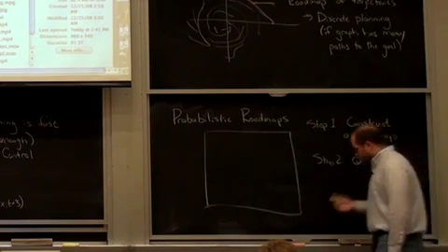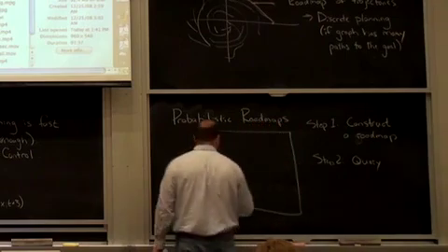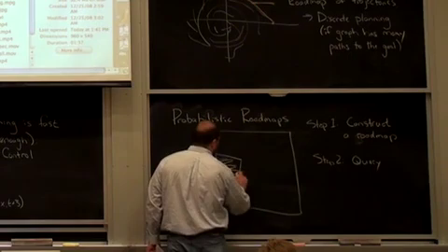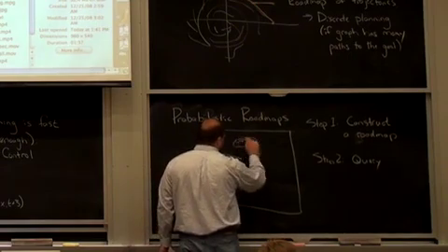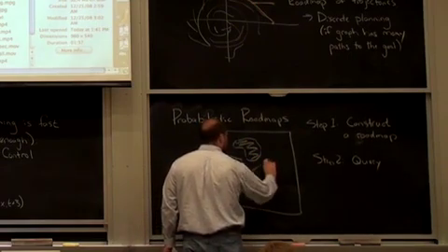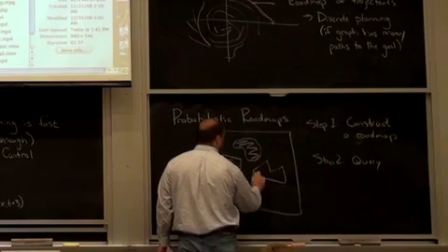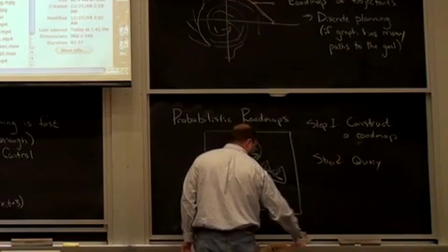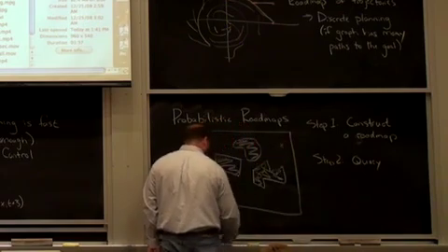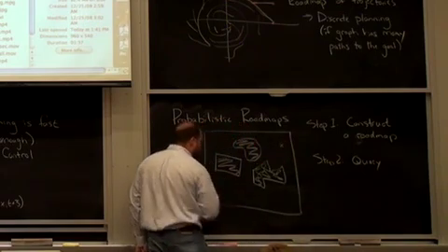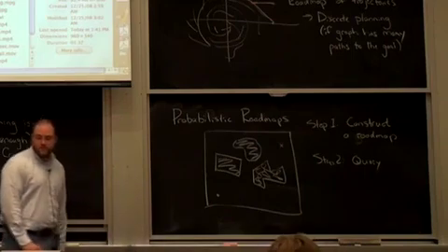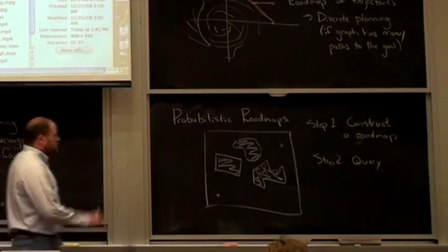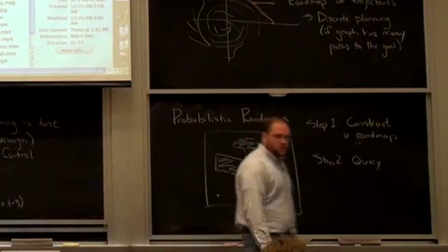Okay? So let's think about that in a configuration space. You know, I've got a bunch of obstacles, and I want to get myself from start to some goal. Right? If I know I'm going to be doing a lot of these things, then it actually makes a lot of sense for me to go ahead and build a pretty good graph, right?